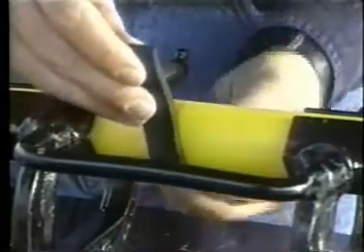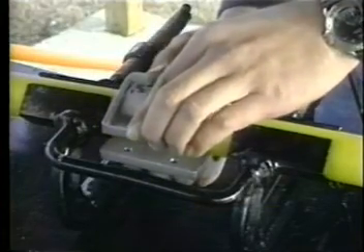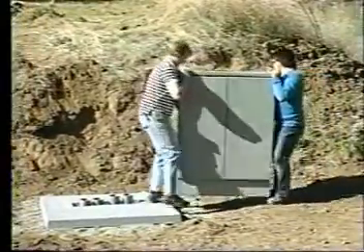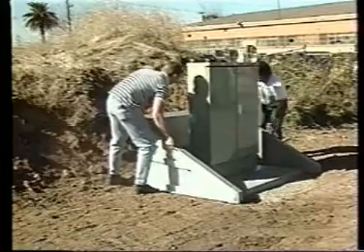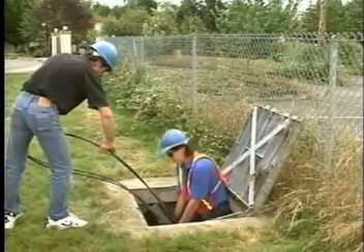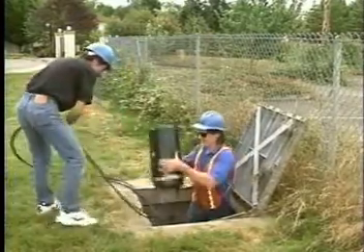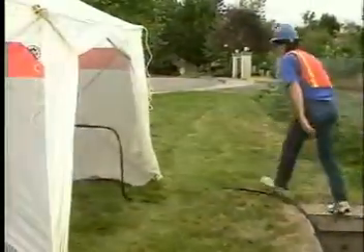When plowing duct, a joint may not necessarily correspond with a fiber optic cable splice point. In these cases, a duct coupler connects duct sections and is buried. At fiber splice points, an underground vault or above-ground pedestal should be placed to house the splice closure. At least 15 meters of cable should be left here to allow splicers to work in splicing vehicles or tents. Slack cable is also important for future expansion or restoration efforts. The excess cable can be coiled, secured, and properly racked with the splice closure.